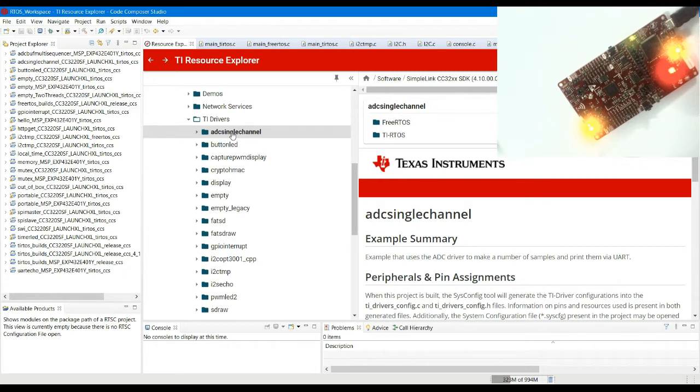There is channel 0, channel 2, channel 4, and channel 6. These four channels are user application channels, and in this particular example only one channel has been taken. You configure the channel for multiple scannings, and whatever data you get in the single channel, you print it to the UART. So this is just a hands-on jump start on how to configure the ADC, how to create a thread, and how to make that ADC access the UART, and through the UART you can print the display data.